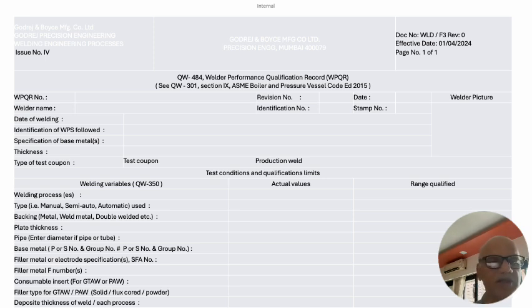If there is a trailing shield, we need to list it down. If we have activated flux, if there are any metal additions through the flux in the electrode, then that has to be noted, whether it is a synthetic electrode or the pure original electrode with only fluxing agents on top of the coating.